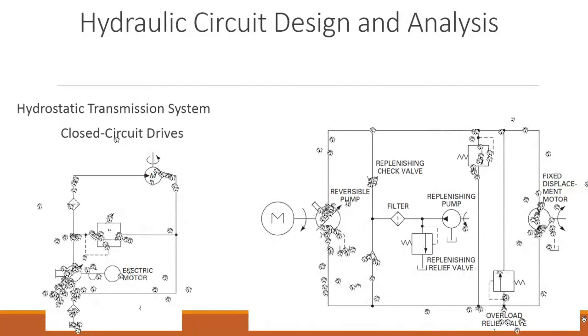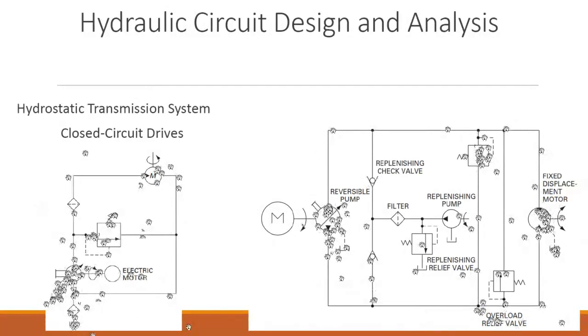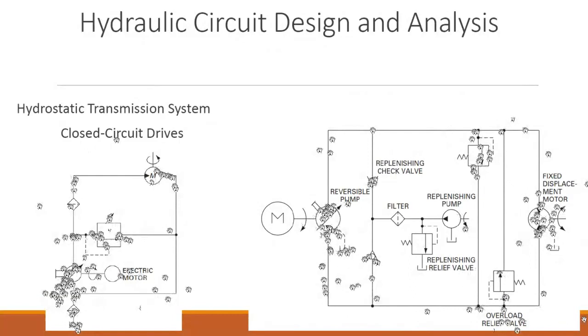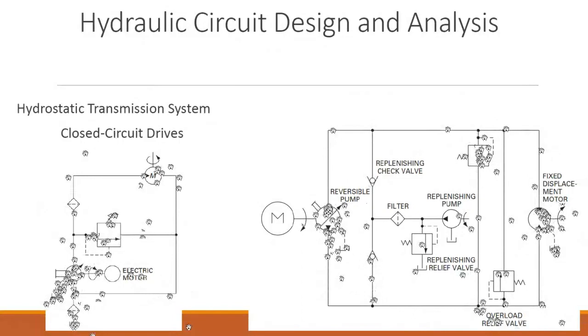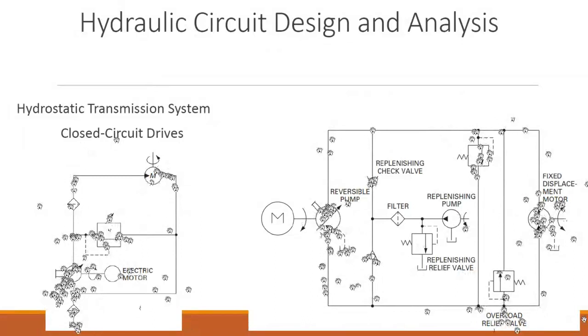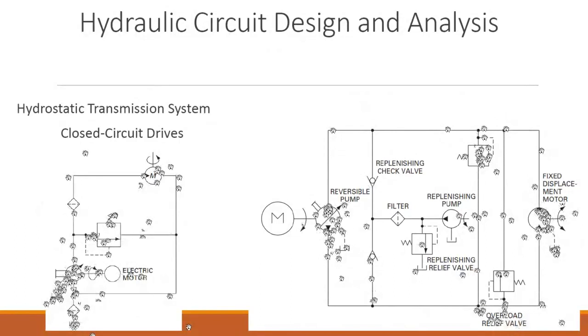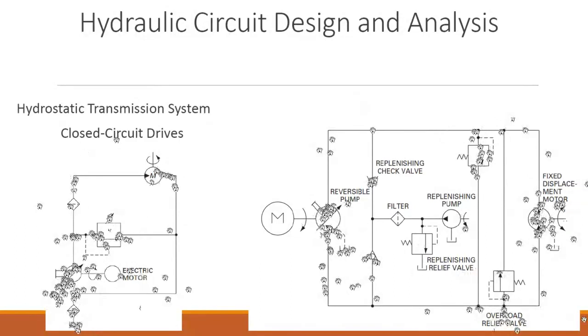So it will not go to the hydraulic motor, and it will not damage the hydraulic motor or the work done, or the load, or something which needs to be turned or moved will not be damaged. So these two bypass lines are just to save the hydraulic motor and also the work, and just keep the oil circulating in the circuit like this, without going to the hydraulic motor.